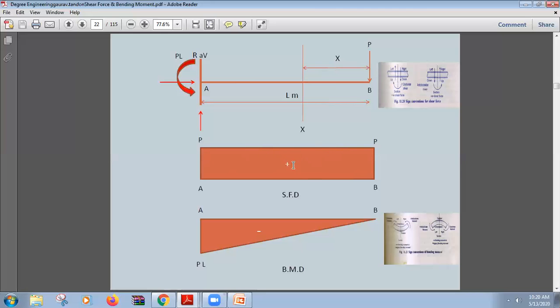And this is positive because the shear force is positive if the left section of the beam has a force vertically upwards. So this is the case. So we have got the shear force diagram positive and vertically upwards. Number one. But our exercise is not complete because we have only determined the shear force, and not the bending moment diagram. So for that we have to come to the bending moment diagram.